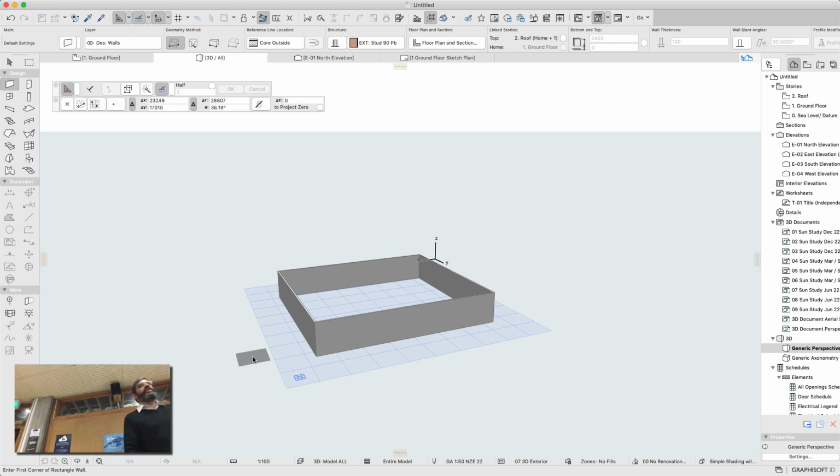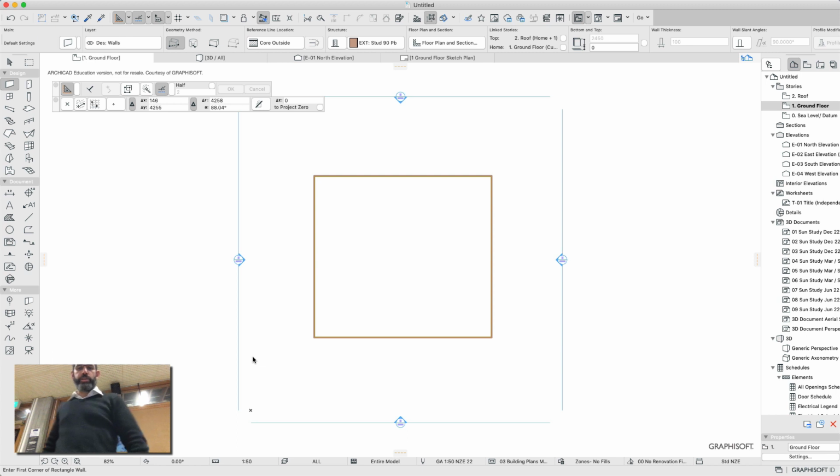So this is our 3D view. Okay, so we've got a 2D view and a 3D view. You can design in the 3D world, which, yeah, that's cool. But designing in the 2D one is a lot more convenient. It's working in plan view. So you can see we can flip between this 2D view and the 3D view. Just pressing F2 will take you back to 2D. Cool, there's my 2D view. And I'm going to press F3 and go to the 3D view.